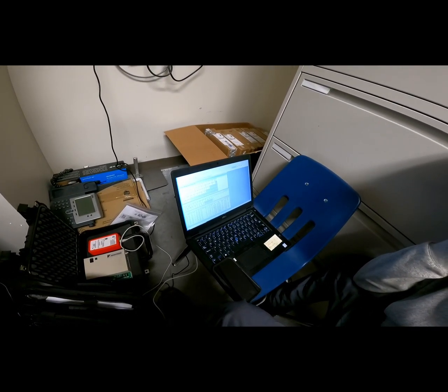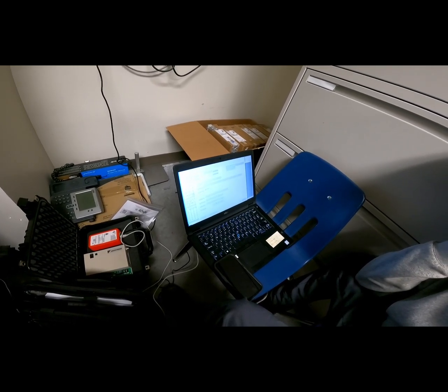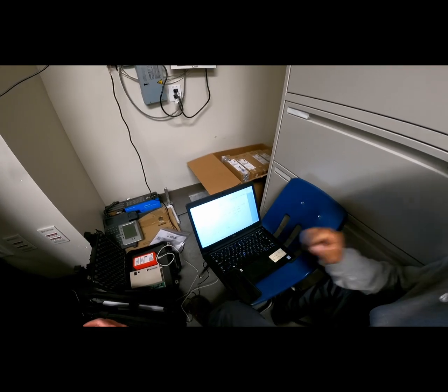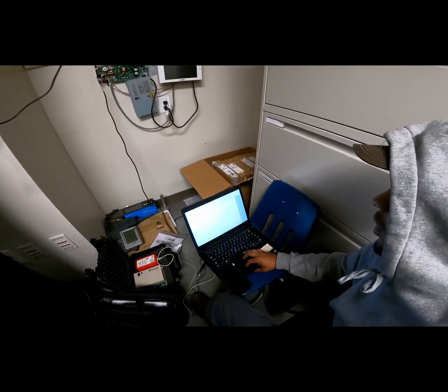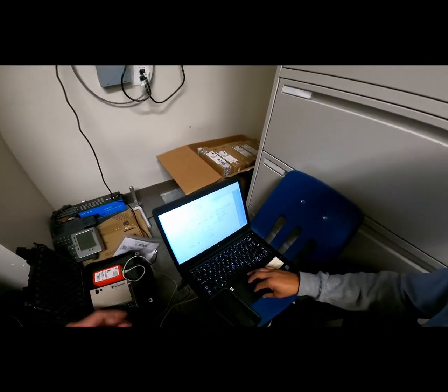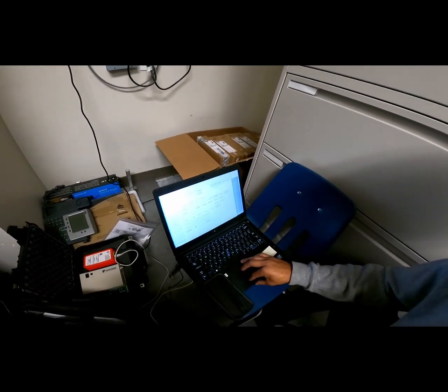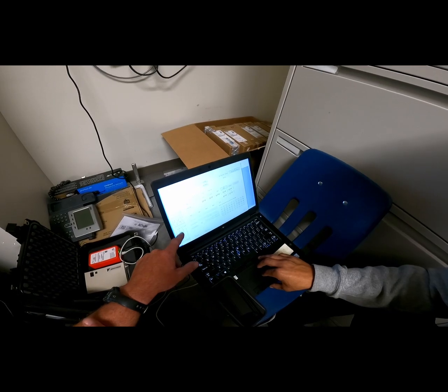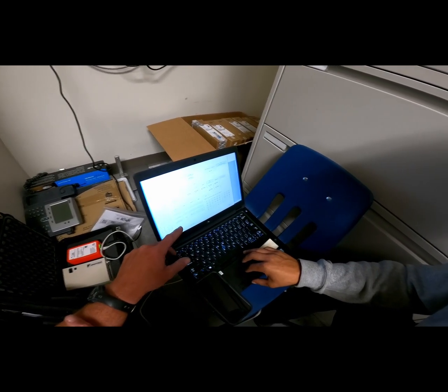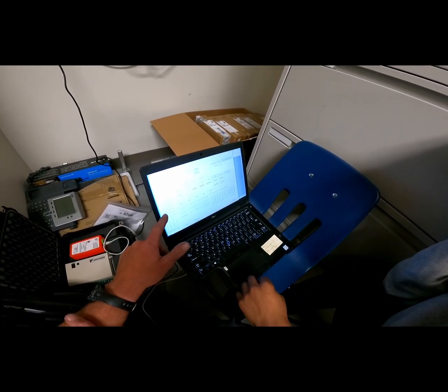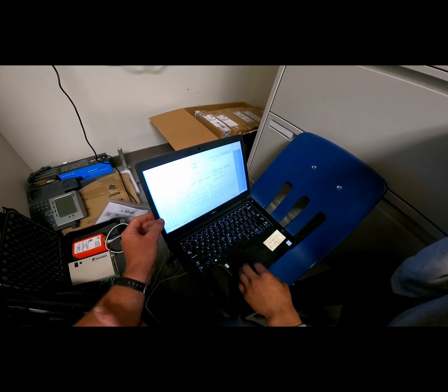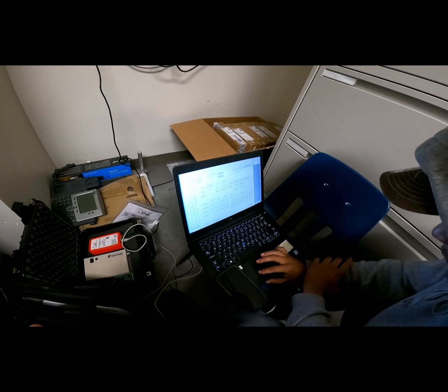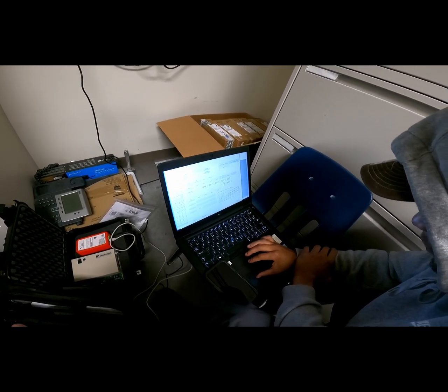And it may show you when the window pops up. Because you can set all, but it'll cause every unit on the entire system to start doing what you're asking for. The first thing we're going to do is set selected addresses. Now, there may be a scroll down menu on this window right here. There was not, but if there is, you need to scroll down and find the entire list of addresses. Make sure you highlight on that list 021 all the way through 028.